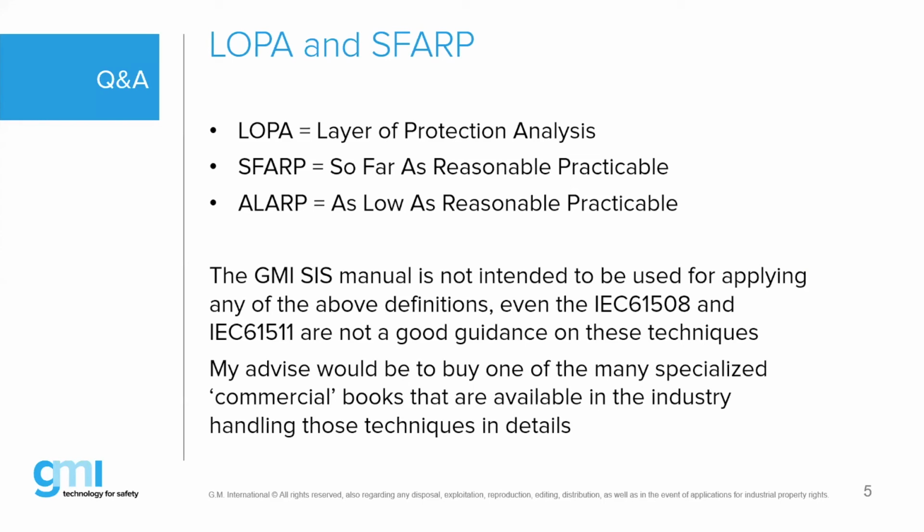Well, I never read that before. Well, I know ALARP, as low as reasonably practicable. Correct. And it's coming from ALARP, as low as reasonably practicable. And for those who are maybe experts listening in to the webinar, I can say ALARP is coming from the book from the HSE in the early 2000s, and they took it over in edition 1 of the 61511. So ALARP is a definition coming from the 61511 definitions here in my slide, but initially it came from a book from the HSE, which is a guideline basically downloadable free of charge for those who would search for it on the internet.